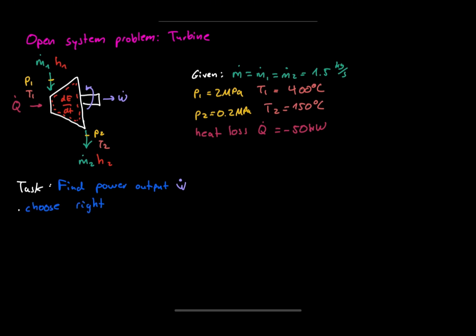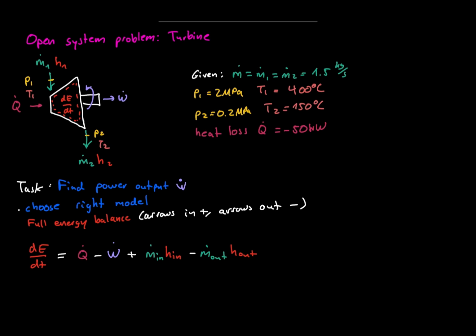First, we identify the system. This is an open system with mass flow. So we start from the general energy balance. The change of energy inside equals heat, work, plus energy carried by mass in, minus energy carried by mass out.